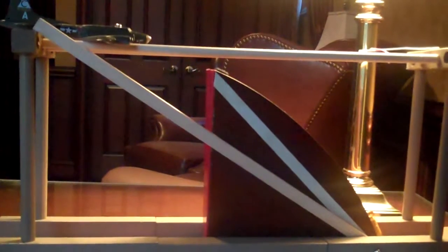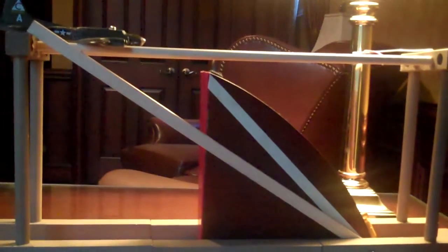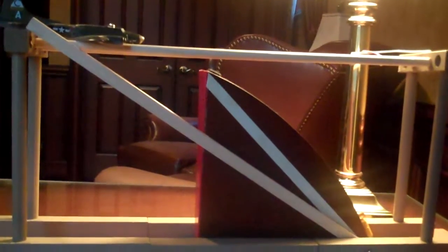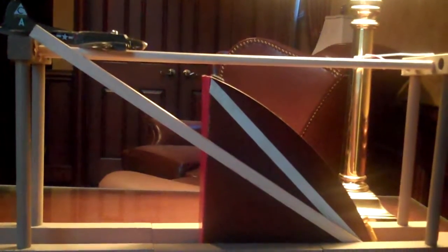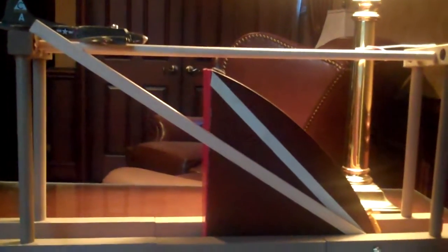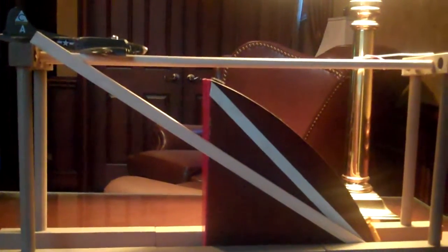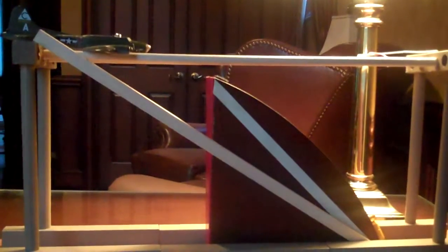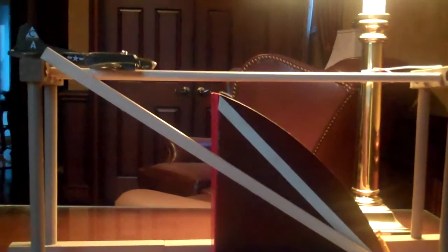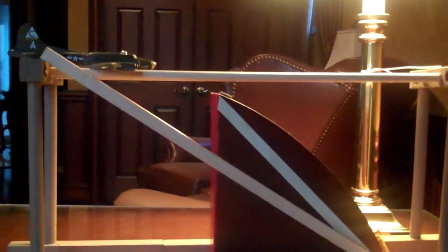The Norden Bombsight takes rates, speeds, times, and distances and converts these into angles to compute the release point for the bomb. Two pieces of information must be obtained from experimental test data. The first is the time of fall. Gravity causes falling objects to accelerate at 32 feet per second, but upward wind resistance causes the bomb to reach a terminal velocity. The shape and size of each bomb determines this wind resistance and how long it takes to fall from a given altitude.